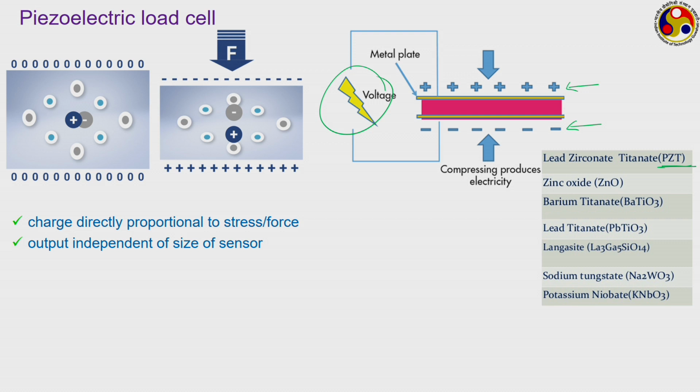That is, the size of the crystal does not limit the amount of force that can be measured. Even with very small crystals, we can measure very large forces, and therefore we can comfortably attach the load cells to any kind of specimen, depending on whatever contour we have on the surface we are dealing with.